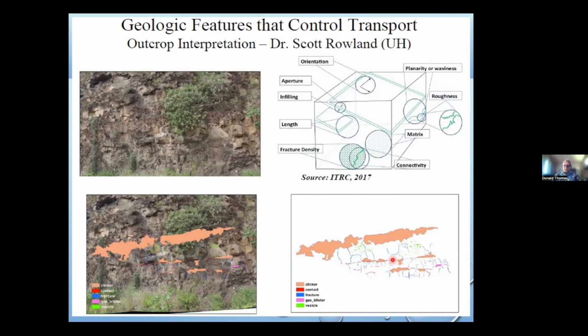By developing a statistically significant inventory of the distribution of these fracture units and determining what their fracture apertures are, we will be able to model how fuel is able to pass through the vadose zone, the unsaturated zone, on its way down to the water table, and actually develop some models to broadly understand how fuel does interact with these features in the subsurface and work its way down towards the water table.